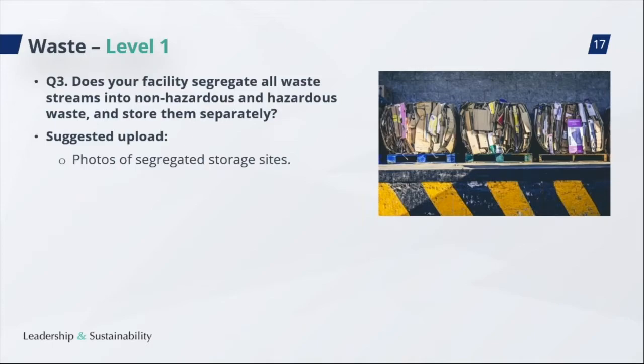Question number 3 goes on to ask you, does your facility segregate all waste streams into non-hazardous and hazardous waste and store them separately? All waste streams must be segregated and stored. Segregating hazardous and non-hazardous waste can prevent unwanted reactions between the waste streams, reduce pollution and harm to the environment and people, and finally help reduce costs because mixing waste can increase the volume of the waste classified as hazardous, which is of course more expensive to dispose of, and thus prevent any unwanted exposure for personnel.